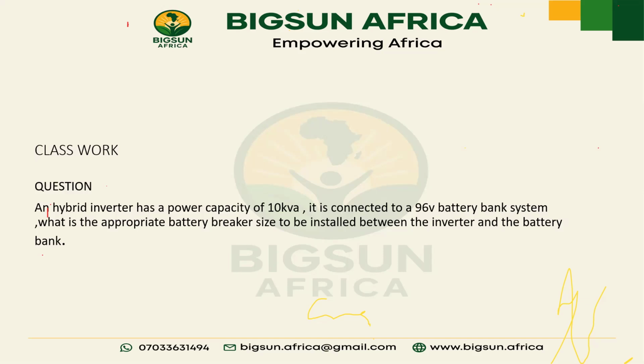So how do we arrive at 8 kilowatts from our 10 kVA? We multiply the kVA by 0.8, which is the power factor. If you want to do your breaker size, you have to calculate it with the actual power.